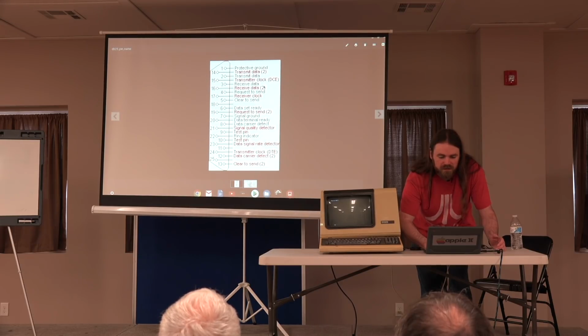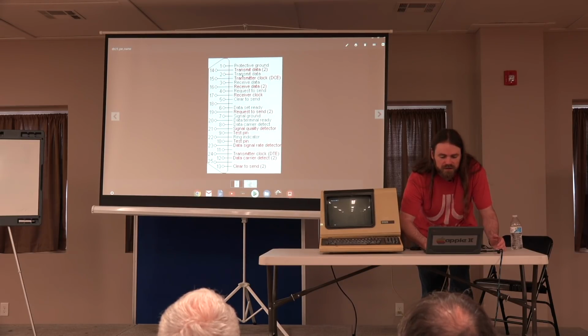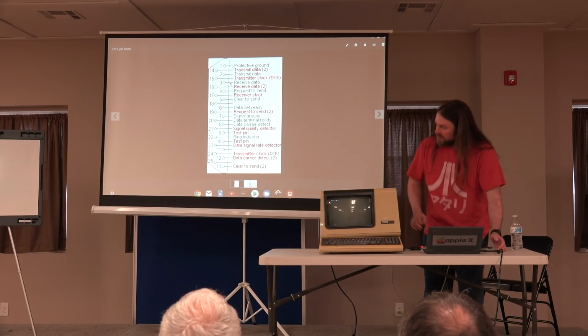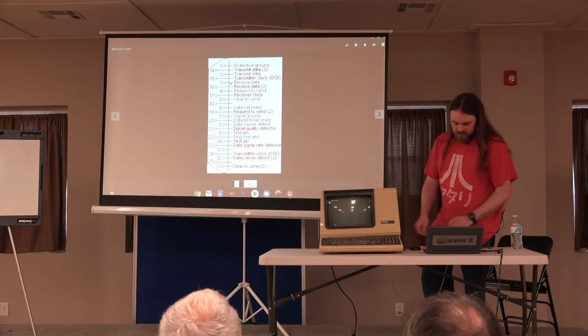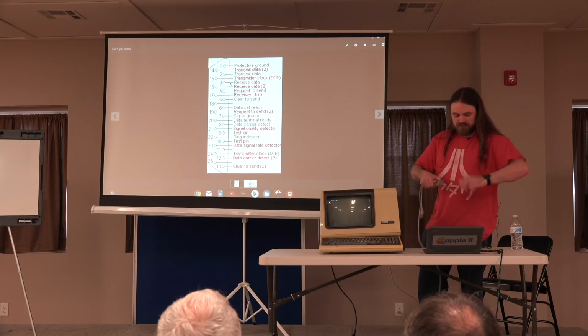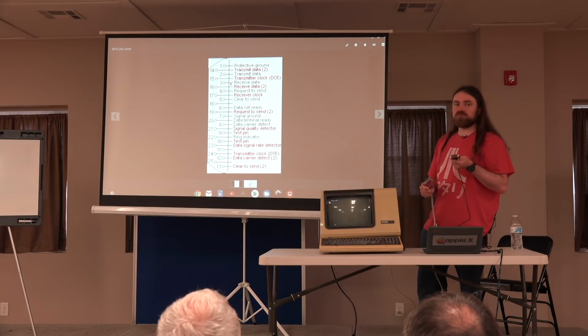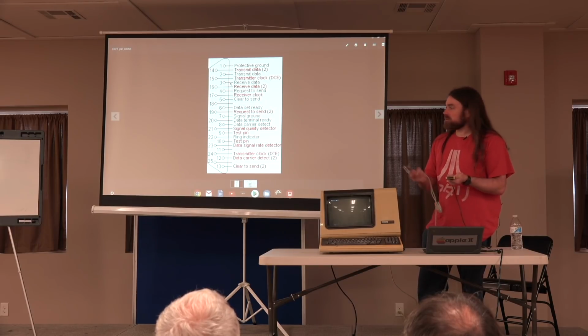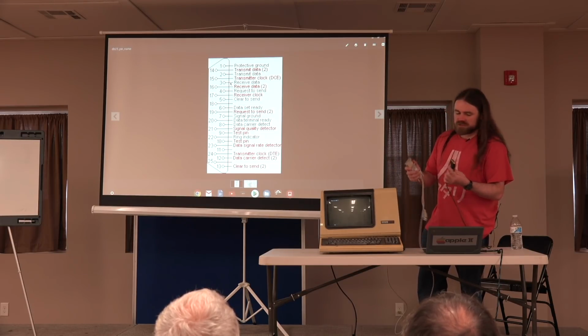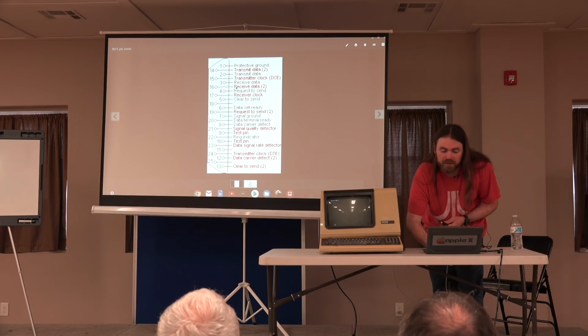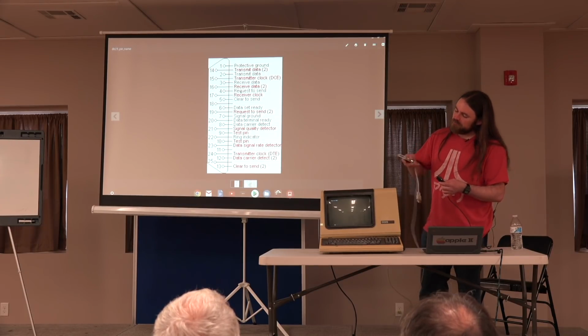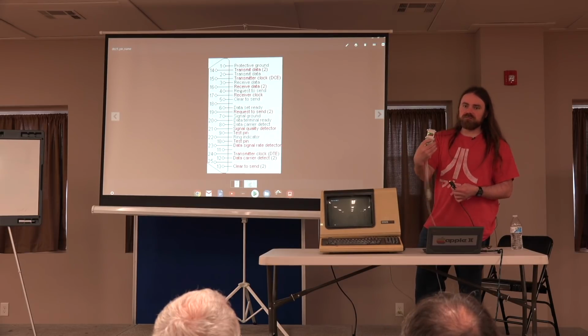You can see that pin 2 is transmit data, pin 3 is receive data. So the terminal outputs on pin 2, it's transmit, and then the computer, after it converts to 25, also transmits on pin 2. So they can't talk to each other. The wires need to be switched. So the adapter crosses over receive and transmit, and then the various other RS-232 control lines get crossed over as well.